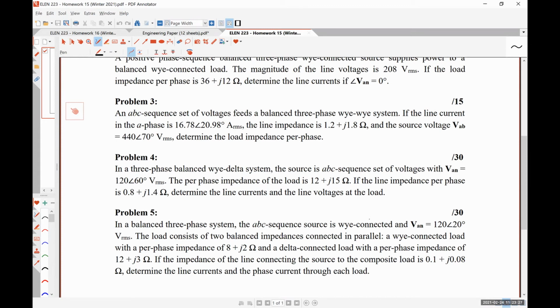If that makes sense. I can definitely write stuff down if you would like me to, or if that explanation was good, we can go with that. Yeah. Okay. Yep. So if I have a Y connected source, I can still specify it by effectively using the delta voltages, which seems hinky, but it's just because it's measured between those transmission line terminals.